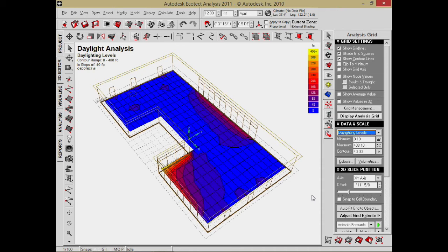If we're going to be working intensely, I'm going to be back there at my desk reading and writing and doing a lot of stuff, we tend to need a higher level of daylighting there. So it'll usually be around 80 foot candles or something like that. Quite a bit lighter than it is at the lobby. Okay? So the more intense the work that you want to do, the higher you want to be. So 80 foot candles, 100 foot candles, super. Your high intensity desk lamp at home, that's like 120, 150, something like that.